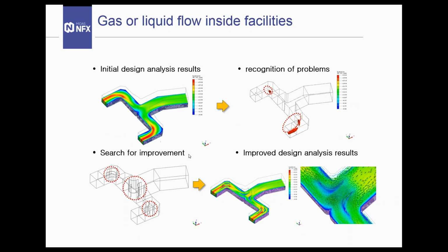Now, in this example, as you can see in the picture, the addition of some thin walls in this position solved the problem and greatly improved the performance of this power plant. With CFD, you can directly add some geometry, remesh, and test your hypothesis to see if it solves the problem, and you can see the results directly. This is a great performance for your company if you're able to solve this, because you're simply saving a lot of money.